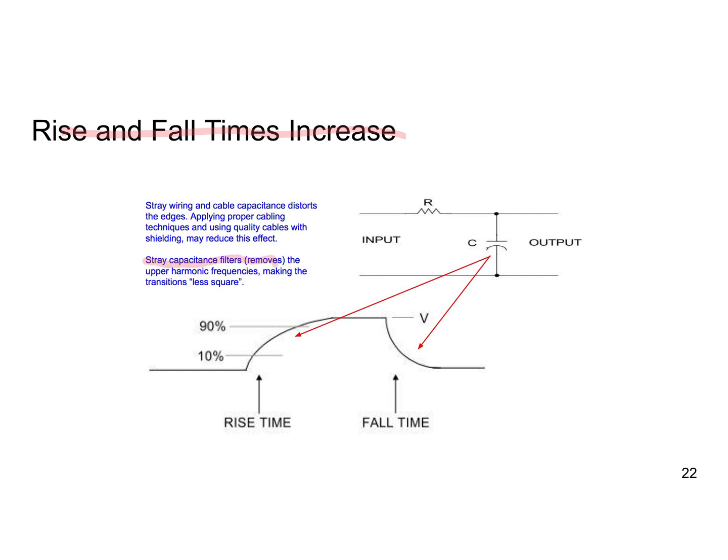You have two wires in a conductor, and there's capacitance between them. There can be inductance. All these things conspire to distort the signal. Again, the rise time goes from the 10% to the 90%, and the fall time from the 90% to the 10%.